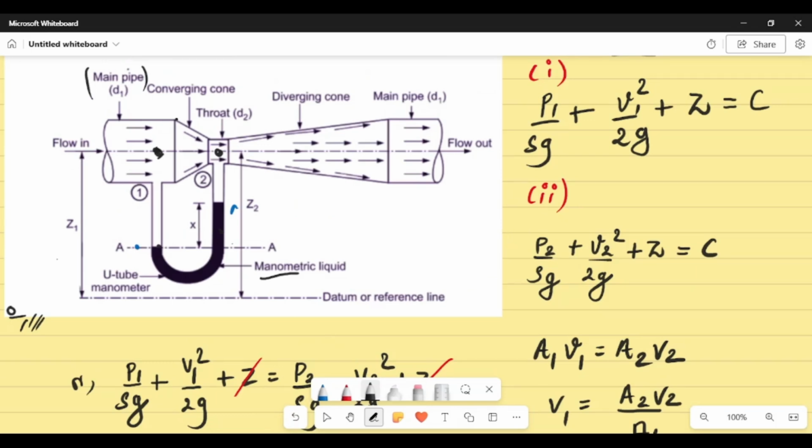First of all, this is the line, so the pressure at this region will be the density of fluid. Let's say we work with the specific gravity. Let's say the specific gravity of this liquid is SL, times the density of water, times Z. So this gives you the H. So rho Z H gives you the pressure at point A on this one side.